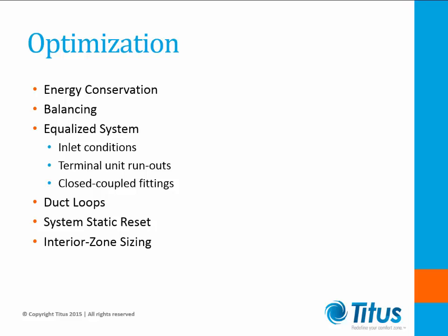Poor inlet conditions can also add pressure and a decent amount of friction to your system. You should always verify terminal unit takeoffs and keep them as straight as possible. Because the primary system has the highest velocities, it also has the greatest opportunity for conservation. Runouts are a perfect example. Size runouts based on primary duct design criteria and not on inlet size. Utilize a smooth transition to the inlet size 3 duct diameters back from the terminal unit. This will allow the air adequate distance to normalize and provide a good velocity profile to the terminal unit without the excessive pressure drop.